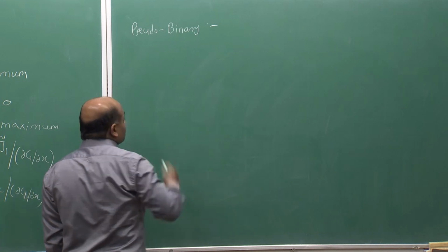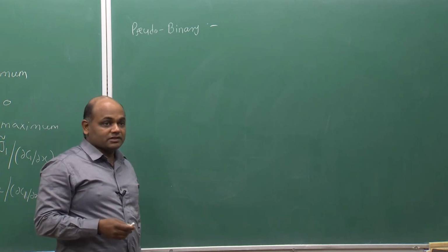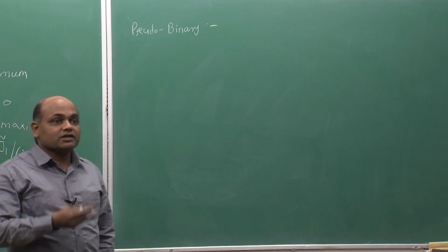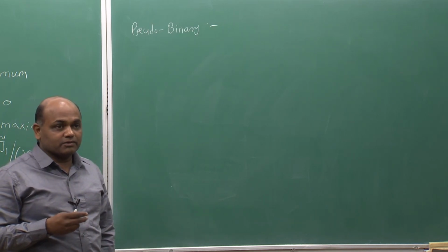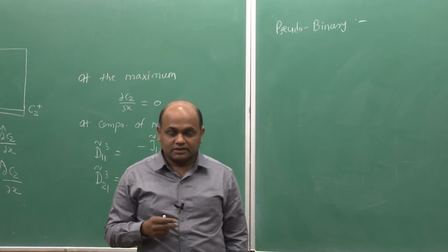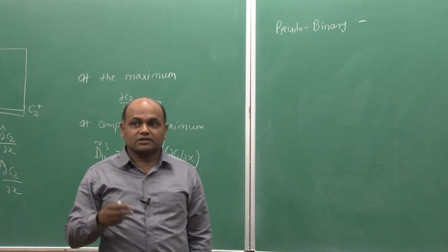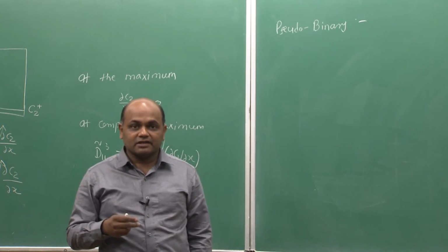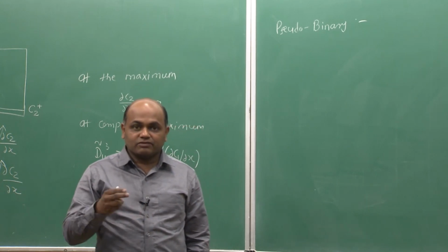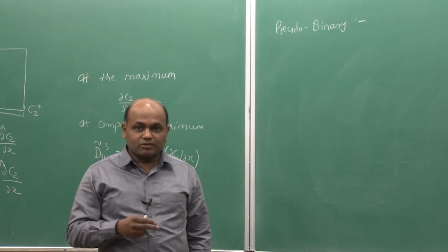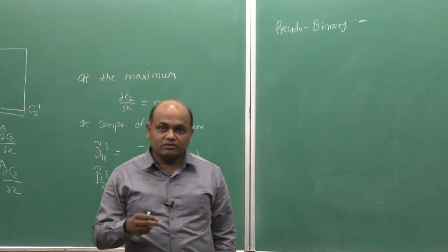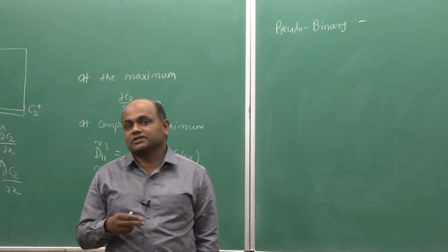In this, what is done is, for example, if we are dealing with a quaternary system, only 2 of the components will develop concentration profiles in the diffusion zone, the remaining 2 will not. So, the diffusion couples are designed such that, for example, component 3 and 2, let us say, have the same concentration in both the terminal alloys, but component 1 and 4 will have different concentrations.